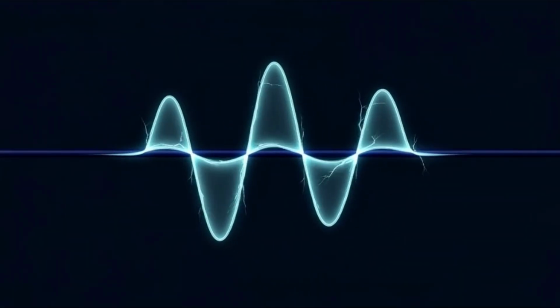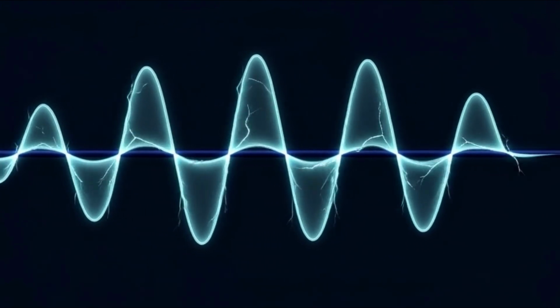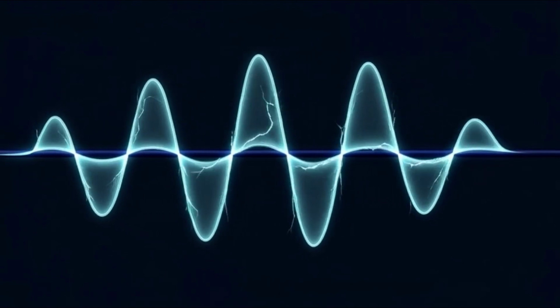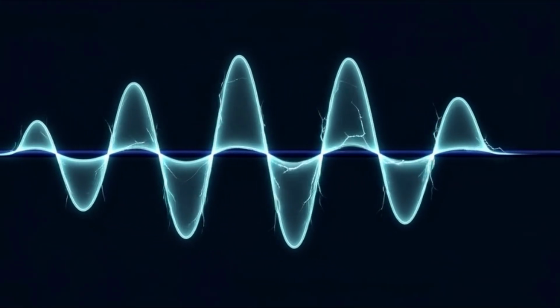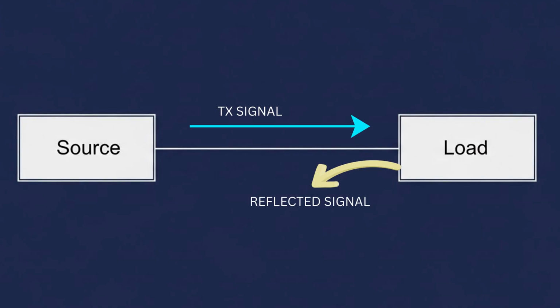At low frequencies, we often pretend circuits are simple. Wires are just wires. A resistor is just a resistor. But at RF, that assumption breaks down. RF signals don't behave like static voltages. They behave like waves traveling through space and along transmission lines. When a traveling wave reaches the end of a line, it expects to see a certain impedance. If the load matches that impedance, the energy is absorbed. But if it doesn't, part of that energy is reflected back toward the source.